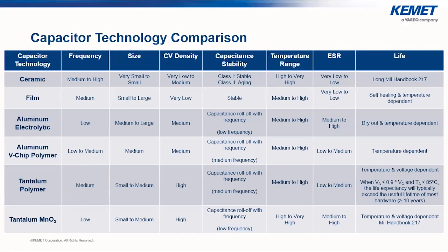This repairing of the capacitor is due to the thinness of the foils used. So when breakdown occurs in a metallized film capacitor, arcing causes the thin metal layer around the fault area to vaporize, and this vaporization process removes the conductive metal layer in the area around the fault. And since the conductive material is removed, a short circuit cannot occur between the plates. This prevents failures of the component. The reliability and operational life of the capacitor significantly depend on its self-healing characteristic.